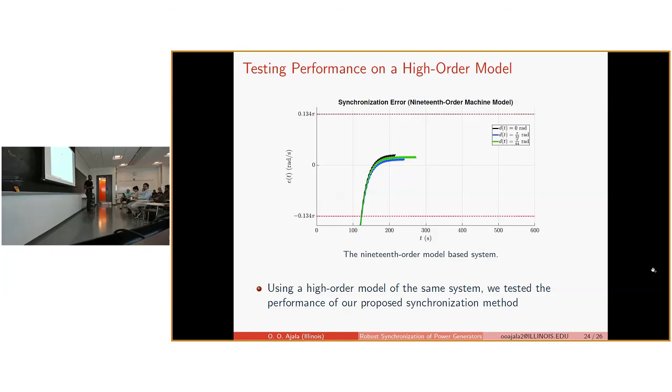What are the measurements that you need from the grid the generator is trying to connect to? It's just the phase? Yes, just the phase. But so it's the phase difference with respect to your node, right? I mean, you need some sort of PMU or... Yes, it's just the absolute phase. So yes, it's a phase. We assume that that information is sent by a PMU to the follower.